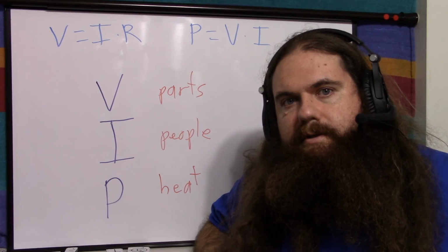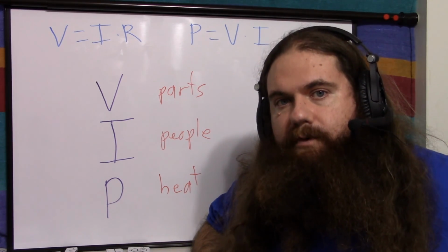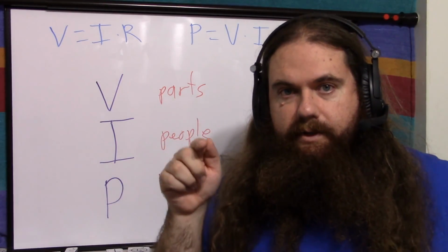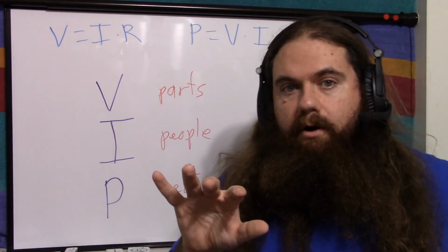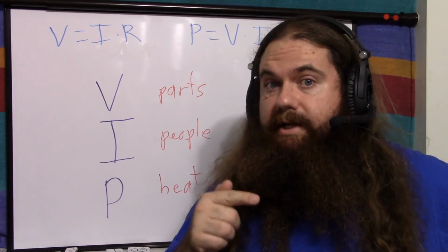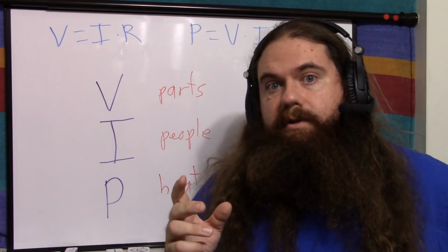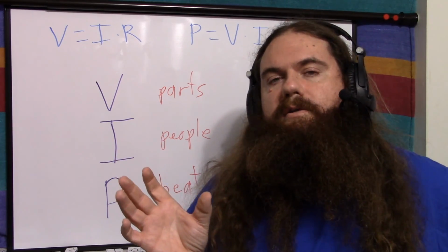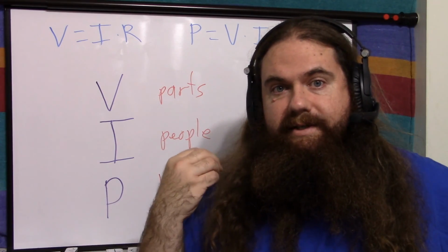If you look at spec sheets for things like transistors, it lists a maximum voltage, in fact, multiple maximum voltages for different directions, different junctions, in addition to the power dissipation. Power dissipation is the heat, but it also lists the voltages that can be sustained. If you look at a resistor, it doesn't. A resistor will only list the power rating because it's only about heat. You can put as much voltage as you want across a resistor, as long as the resistance is high enough so that the current is limited so it doesn't catch fire.